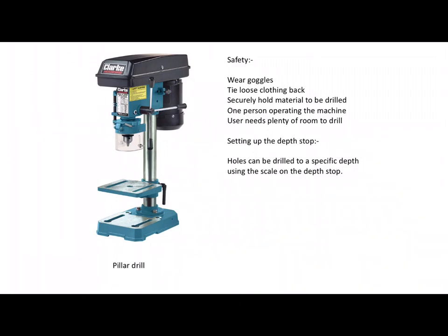Another aspect to using the pillar drill is if you want to drill holes a particular depth, then you want to use the depth stop. And the depth stop has a scale on it that allows you to set it so that it drills holes the same depth every time you use it.